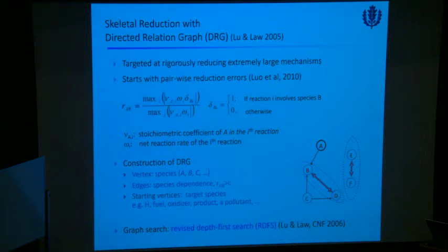There's a common trick in this reduction: people tend to think if this quantity says there's some big relation from A to B, then B must be retained. But that's not the logic. If you see A goes to B with big flux, of course B is important to A, right? But otherwise, if the flux from A to B is small, the key question is whether B is not important to A or not. Because what you need to do is to eliminate species, not to retain species. You have to make sure the elimination is safe.